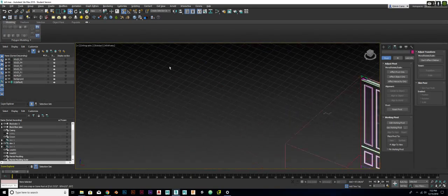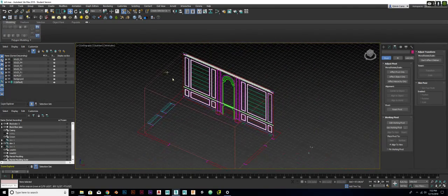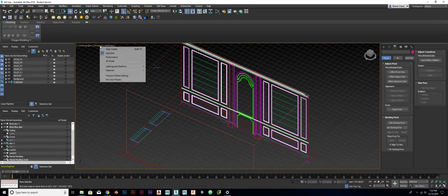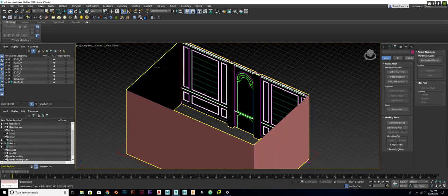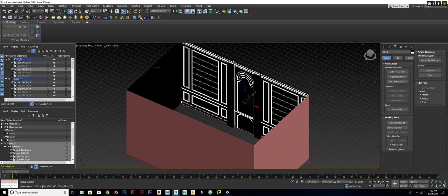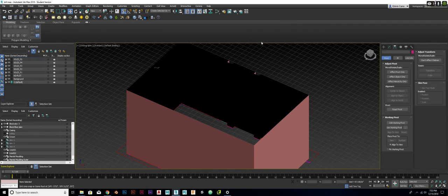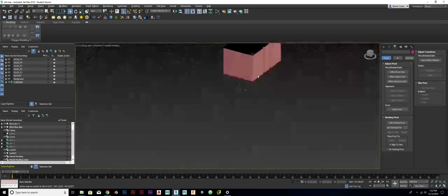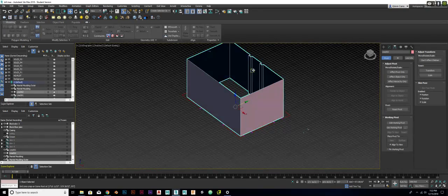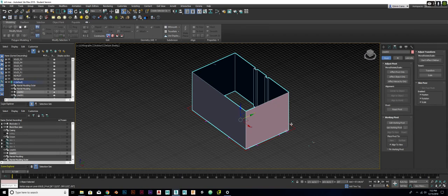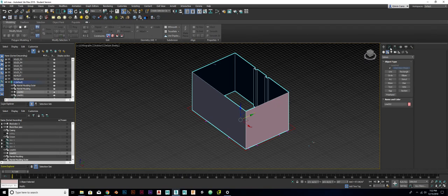Okay, so now I'm going to use a line tool again, and I am going to trace this out. First thing is first, I'm going to actually hide this, just so I can draw the line more appropriately without it snapping to where I don't want it to be. So let's hide that. And you see how it's dark on the inside? I think that's the problem that we were having before. It thinks this is the shape, not this. This is the hidden part, this is the seen part. We actually want it to be the opposite.